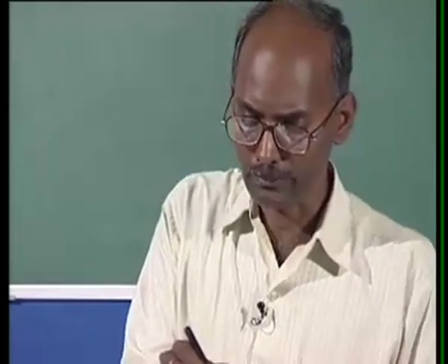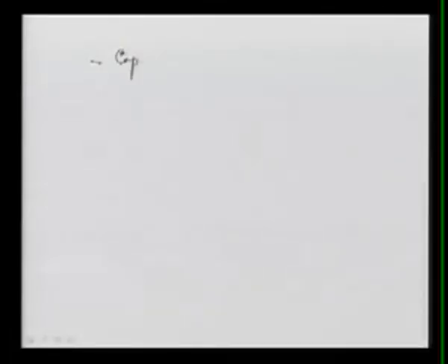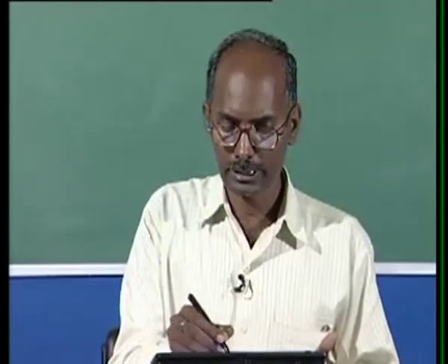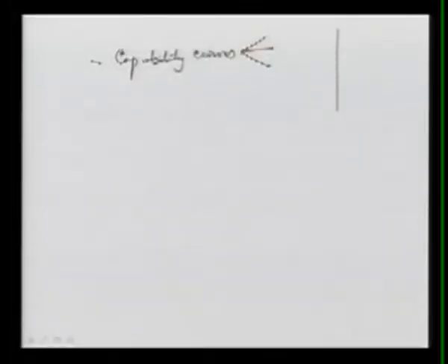First we discussed the capability curve of generators. This is a capability curve. In that we saw the various limits of an alternator, that is the field heating limit. The three heating limits I derived, and if you remember, here I draw P and here Q. So this is your field heating limit, then we have the armature heating limit, and finally here it is your end heating limit. So this is the capability curve of the alternator. I derived it, and then I explained it in detail.